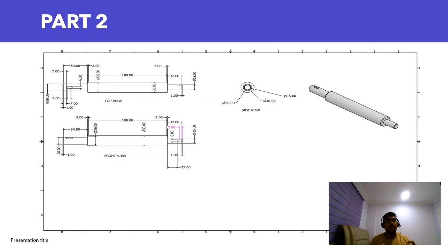Next, I made an indentation on the first piece of the drive shaft, which has 3 pieces, for the pin to be inserted, by making a plane that is offset 6mm from the center plane using the offset from plane option. Then I made an oval shape using a slot with the dimension of 7mm by 6mm, 7mm from the starting point, as you can see from the front view, and I extruded it upwards by 4mm.